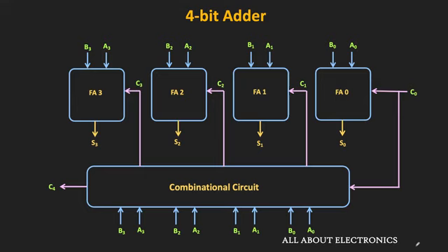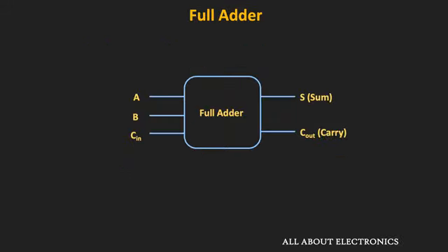To understand this carry look ahead adder, first let us understand when a particular full adder block generates the carry bit. In this full adder block, there are only two ways the carry gets generated. One is that the block itself generates the carry based on the input combinations, and second is that it propagates the incoming carry to the next stage. Let us understand these two terms, carry generation and carry propagation, because they will help us in designing the combinational logic of the adder.